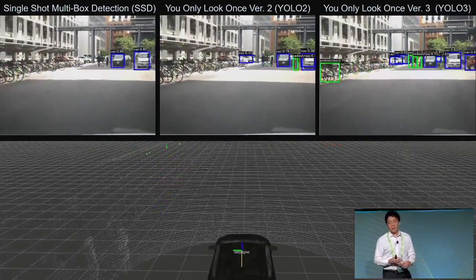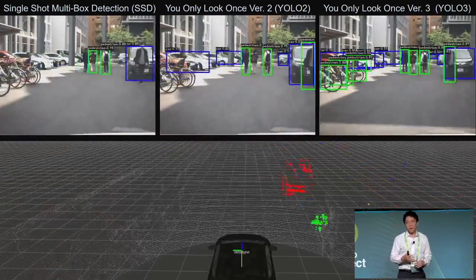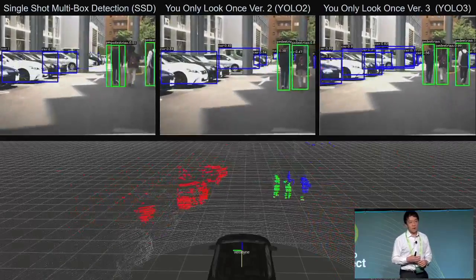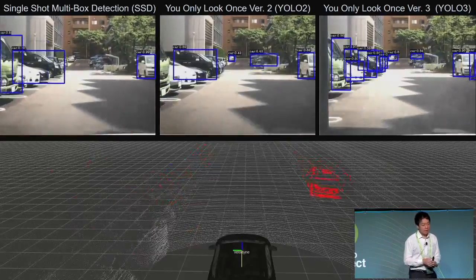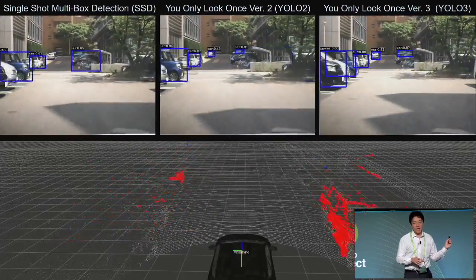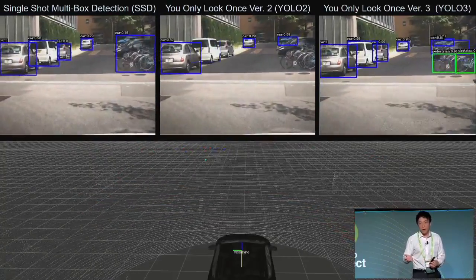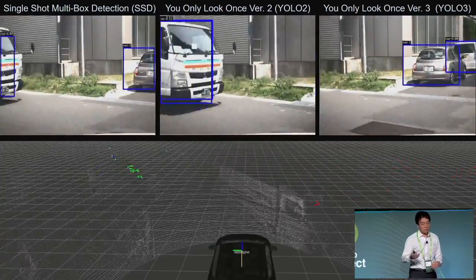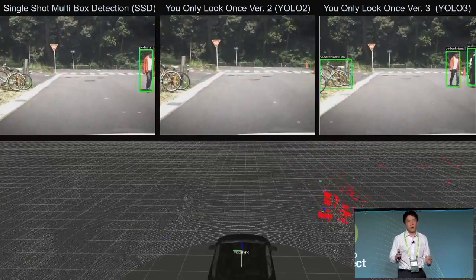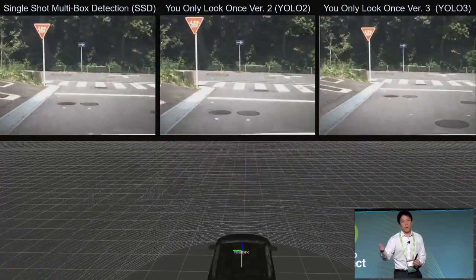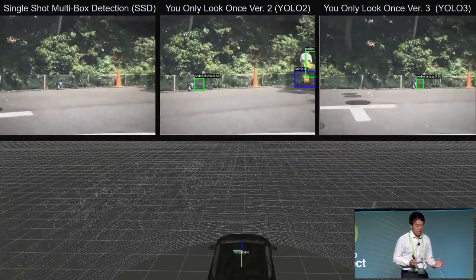And perhaps this is the most popular area of autonomous driving, computer vision. Every year, new deep learning algorithms are presented at conferences, so Autoware always tries to update the algorithms. Like 3 years ago, we had SSD, but last year, YOLO 2 came up. Then this year, YOLO 3 was presented. So the Autoware community always tries to implement new algorithms so that, for R&D purposes, you can also access the new algorithms in the actual platform.